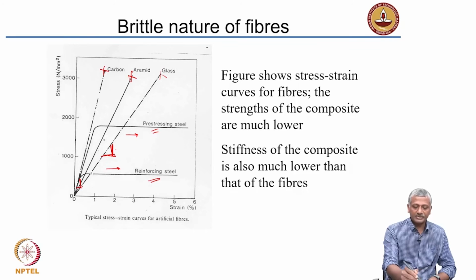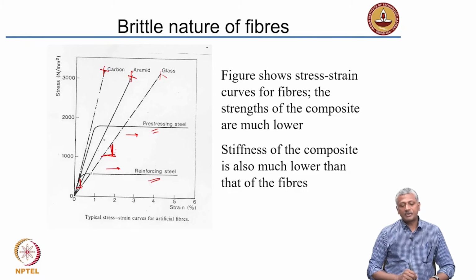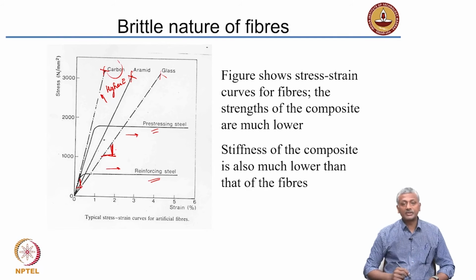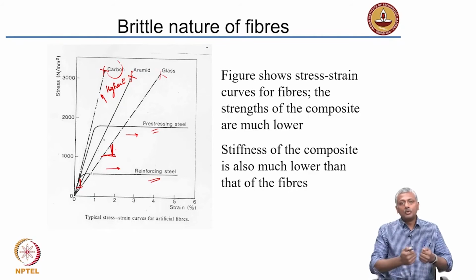So, steel has a high stiffness, whereas the glass fiber reinforced plastic has a low stiffness. When you go to carbon fibers, stiffnesses increase, higher stiffness which is closer to that of steel, but the problem is it's extremely brittle behavior and simply no plastic deformation before failure.